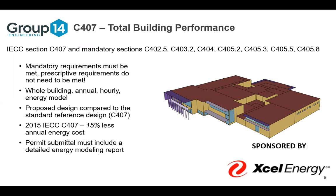So other requirements, the whole building annual hourly energy model must be provided. So you can't just be doing a calculation. It has to be an hourly energy model. The proposed design compared to the standard reference design, all of the inputs into your energy model are listed. And then C407 has requirements for your proposed model, how to model the baseline model in comparison. We'll get into some of those as we keep this moving.